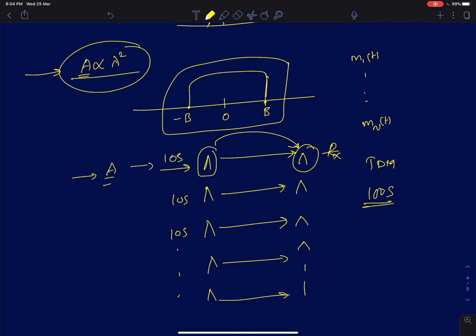Even wirelessly, without modulation also, he can do it. The only problem right now, we said, is that the antenna sizes become impossibly large. In fact, you can't transmit a DC signal wirelessly. So that's an obvious thing. For a DC, the signal has to be constant. It has to be constantly received, and therefore you can't transmit it wirelessly as a DC. So maybe you can say, let's say we have this data here. Maybe I can ensure the DC is removed and transmitted. I can just remove the DC content and transmit it. So this is one mode of transmitting.